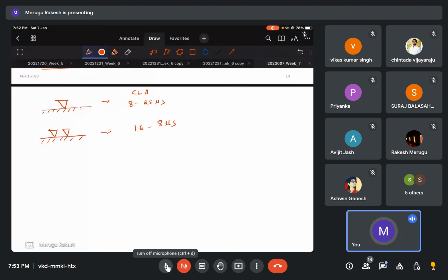Similarly, if I go on increasing these triangles, the surface roughness range, or the tolerance in terms I can say, will decrease. Suppose I have four inverted triangles, that is less than 0.025 microns, extreme tolerance, an extreme surface finish I have to maintain. Just remember that the inverted triangles resemble the CLA values. If the triangles are more, then the surface roughness is minimum.